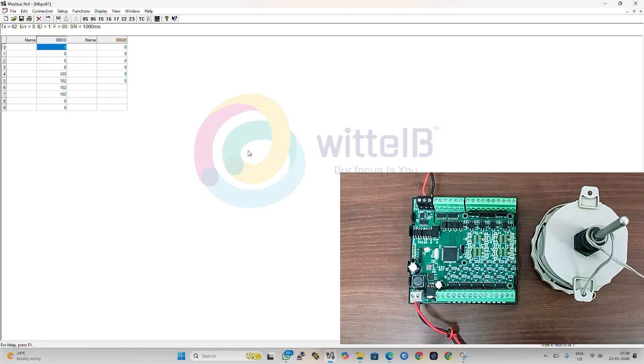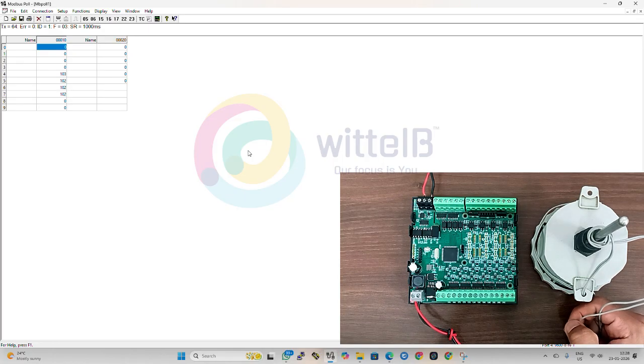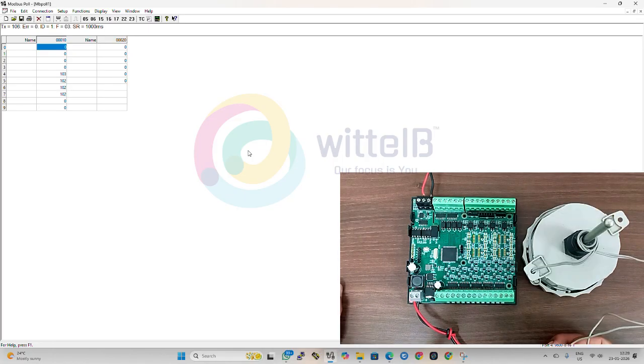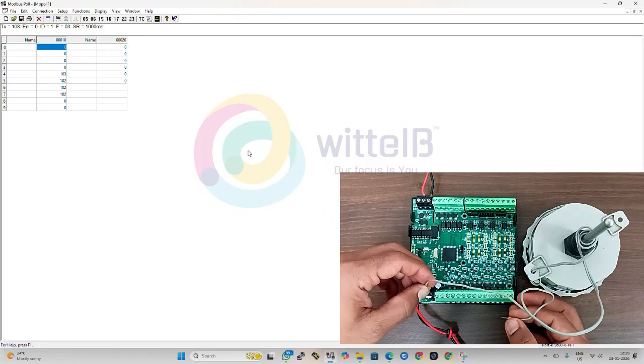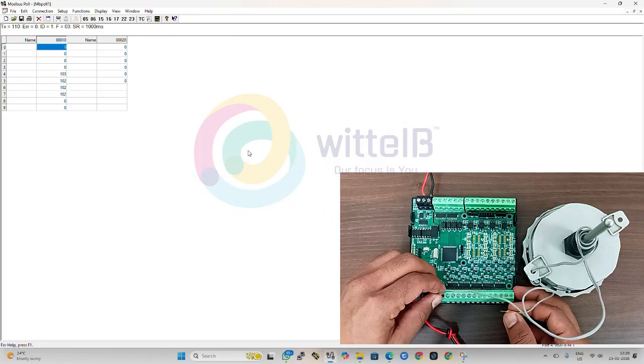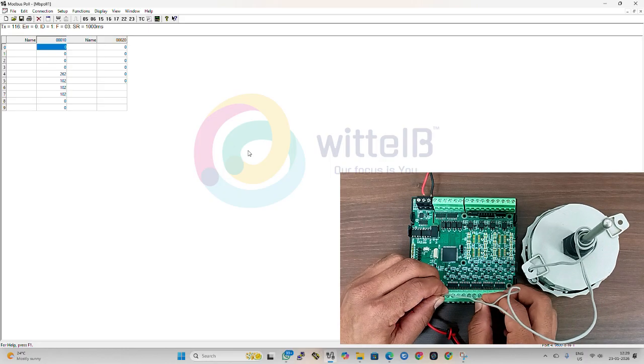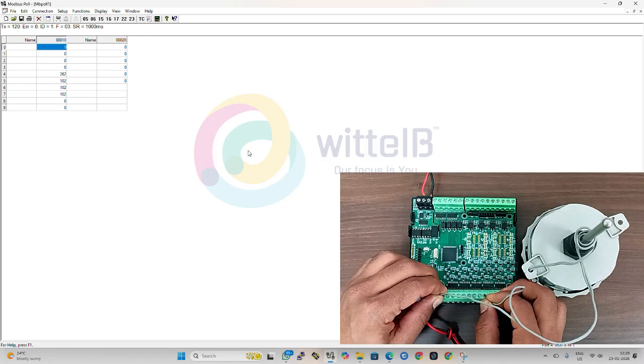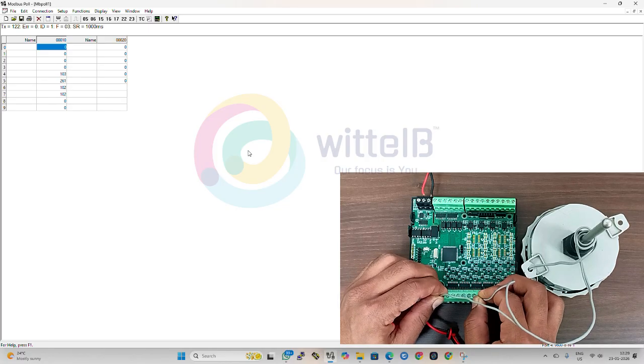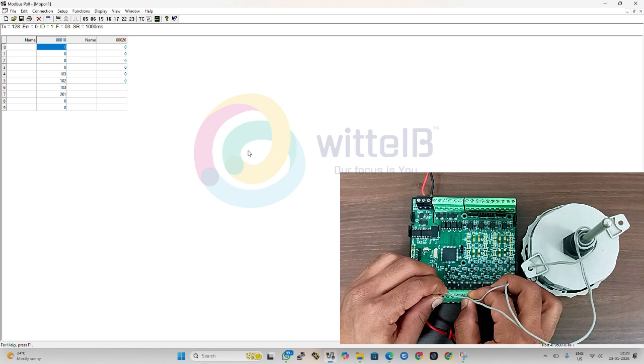For this NTC sensor, in the UI channels, for connecting every sensor, the ground should be common. So here we need to take the ground as a reference for the common. At the 5th register I am getting 26.2 as a temperature. At the 6th also I am getting 26.1, same as the 7th and 8th.